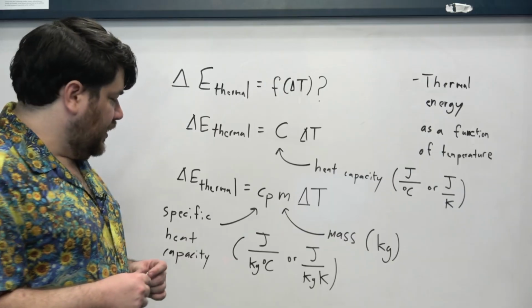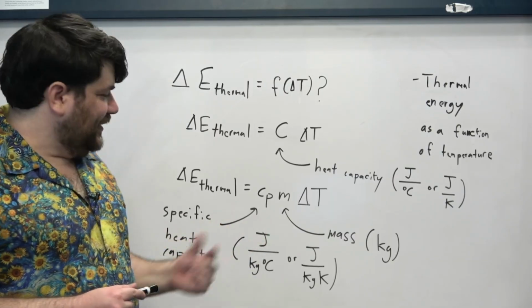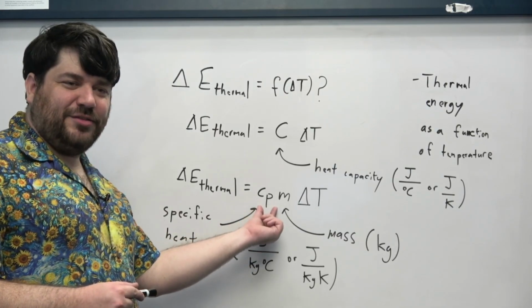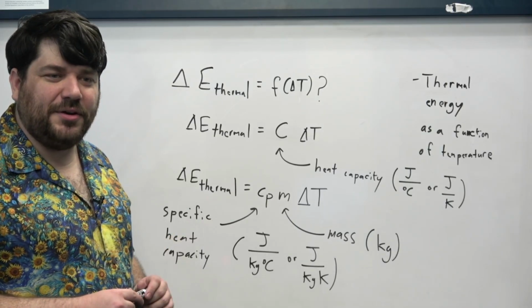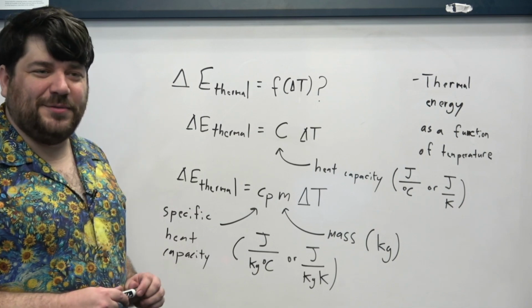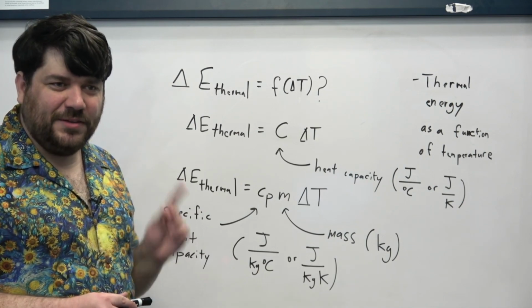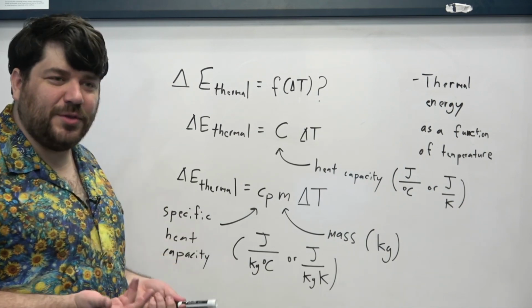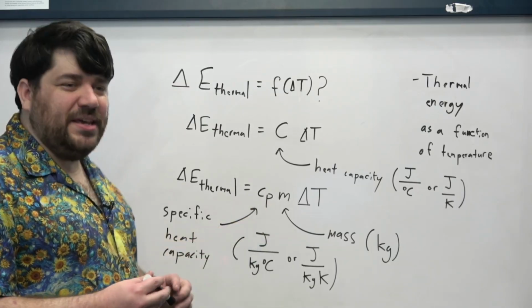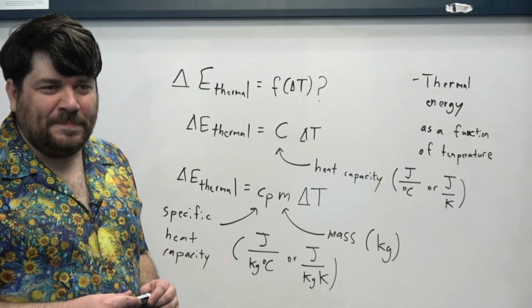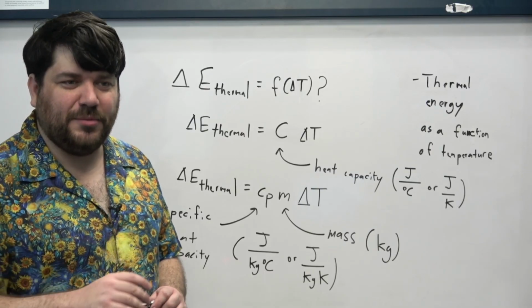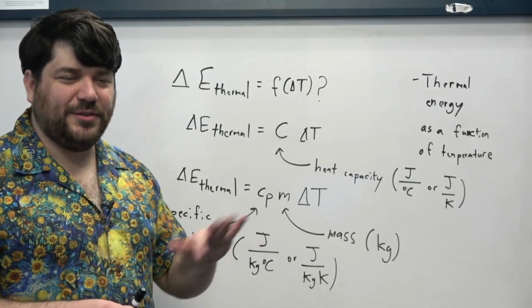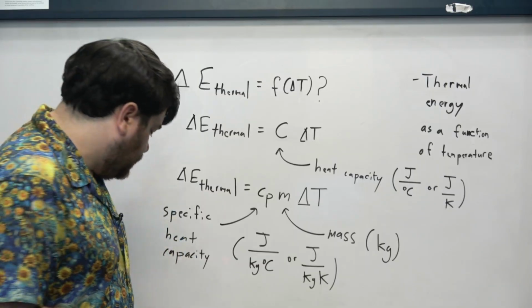So ultimately speaking, the fudge factor, the experimentally derived thing that we've offloaded all the physics onto, is now the specific heat capacity, all right? And so keep that in mind whenever you see expressions for the thermal energy. This CP, this specific heat capacity, plays the same exact conceptual role that the heat transfer coefficient and the thermal conductivity do in the equations where we use them. All right.